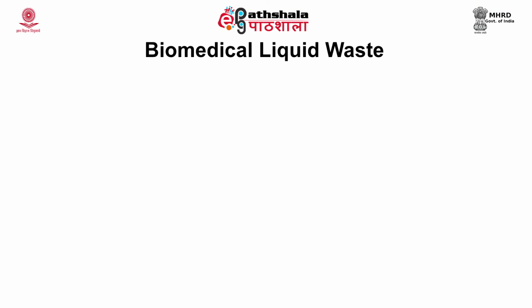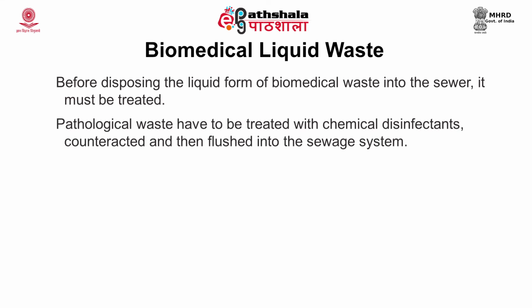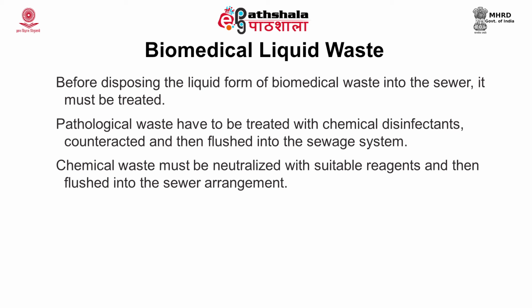So far we were discussing the solid waste generated from biomedical waste. Now we look into the liquid waste, which is also a part of biomedical waste. Before disposing of the liquid form of biomedical waste into a sewer, it must be treated. Pathological waste has to be treated with chemical disinfectants, neutralized and then flushed into the sewage system. The chemical waste should be neutralized with suitable reagents and then flushed into the sewer.